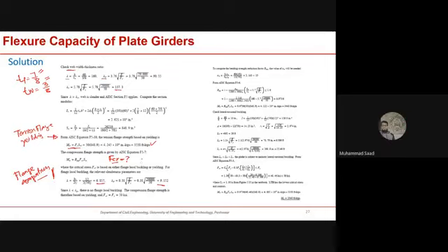Sir, equal to yield strength. Yes. Now this is already there, so you can use this one. Now you need RPG. You can calculate this reduction factor from here, and to calculate it you need AW. When you calculate this one, you check with the limit, then you plug that value in. Now you have two capacities: the first is coming from here, the second is coming from here. In this case, you do not have continuous stiffeners.